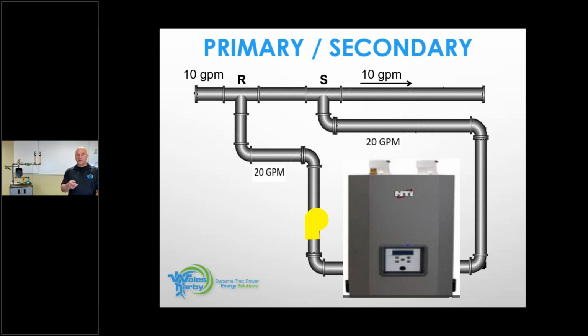Here we go. So, large diameter pipe, supply, return, boiler, 10 GPM out here, 10 GPM out there, 20 to the boiler. I'm going to say that this is 4 to 8 pipe diameters apart. And what's happening right now between those 2 T's? Forward, reverse, or sitting still, and what's my rate?